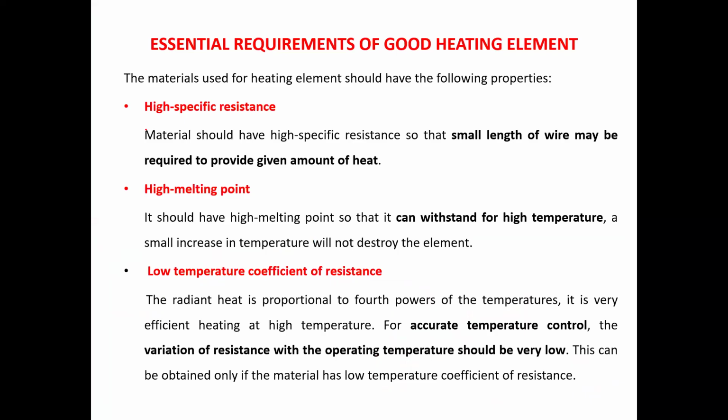Next thing, what are the essential requirements of a good heating element? I would like to have some heating element now. That heating element also will follow some requirements. It will have a high specific resistance. We can choose a high specific resistance, which means a small length of wire may be required to provide a sufficient amount of heat. That's a crucial point. The melting point is also high in order to withstand higher temperatures. Melting point. What's the third option here? It has a low temperature coefficient.